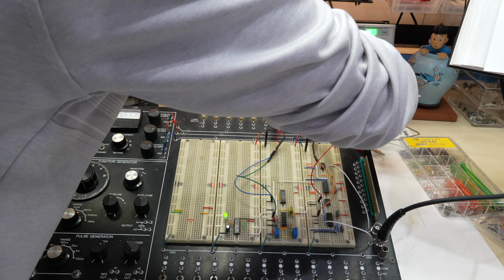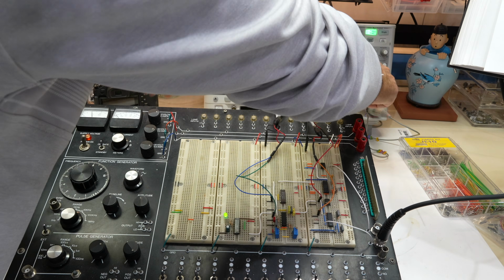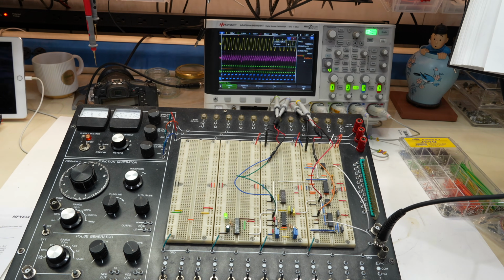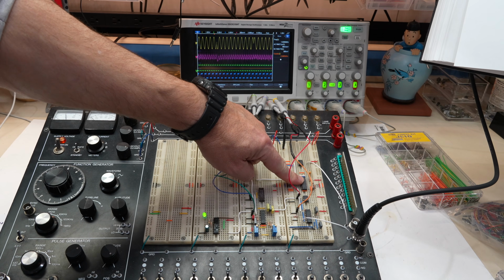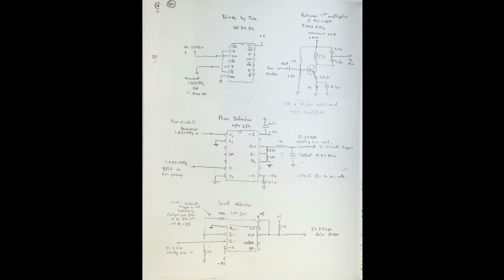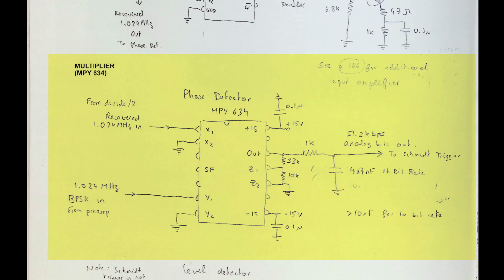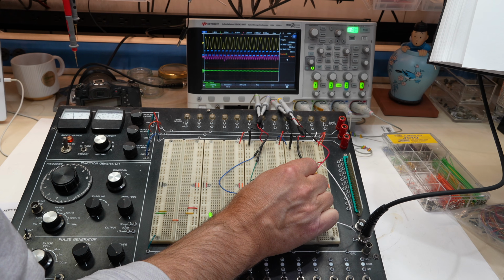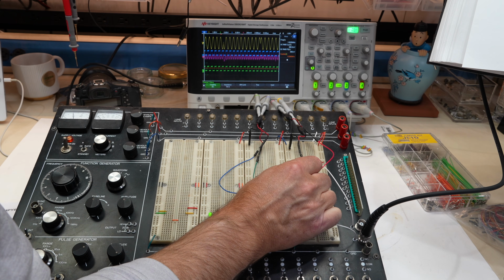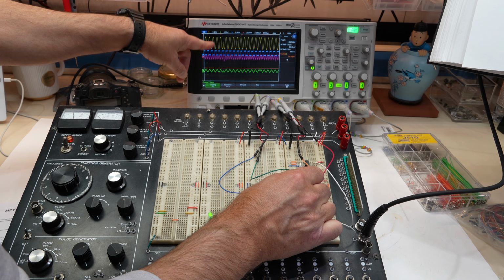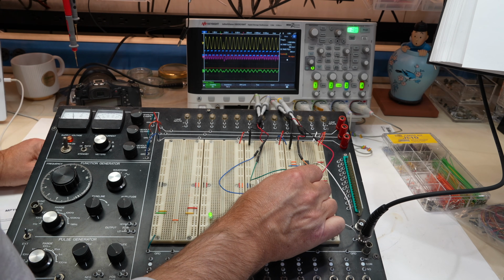And now I want it divided by 2. There you go. So here's my carrier. Then it goes back into this circuit, which is another multiplier. This multiplier is the centerpiece of the decoder, used to multiply the BPSK signal with the recovered reference signal. We use the same analog multiplier IC as we had in the squarer. Well, we have one input of the multiplier. That's our recovered carrier. The other input is our original signal, the same as the yellow one. I'm going to multiply those two.